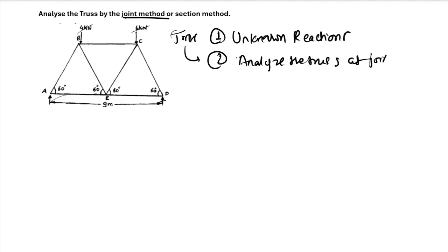So you want to try the points where there are forces given or magnitude of forces given, like the force 6 and reactions. But if there are fewer points, then you can also prefer E, where you can find the unknown forces without any magnitude of the force given. But if there are points where magnitude is given, you want to try at that point first. So like analyzing the truss at the joint.